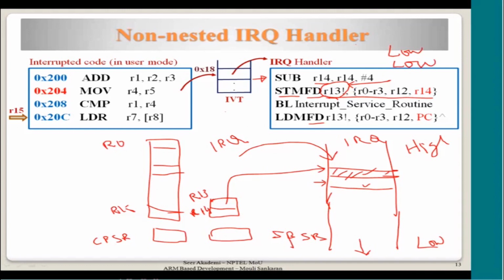It's a store multiple, right? So the memory cycles are multi-cycle: non-sequential and sequential. If you understand, once the sequential cycle is started, it is going to do a sequential access of memory, either for store or load. So in this case, it is going to store. It is going to start from a lower address to a higher address. Why? That is the way the memory can increment the addresses and then store them.